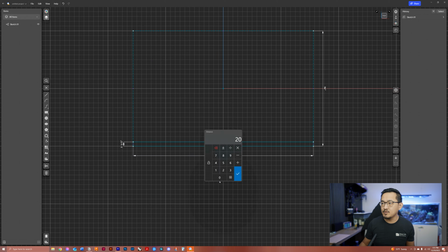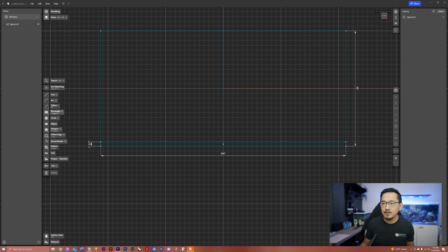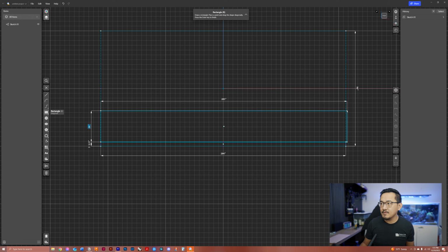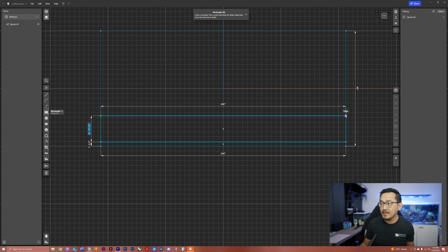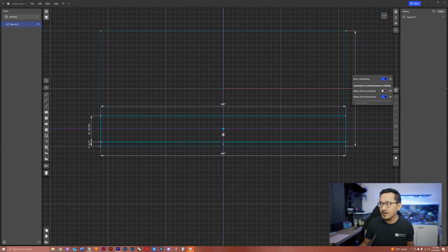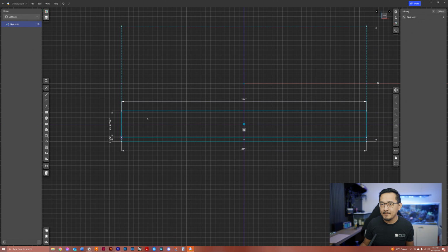It's great that you go back and check your work before moving on, making sure that everything is tied together and moving correctly. So let's go back to 204. And then I'm going to draw the upper cabinets. I'm making sure for these rectangles that I'm hitting that edge point there, as you can see. I want to make sure that the point is locked onto the edge. That way it gives me this automatic coincident constraint. Instead of going in and doing it manually, it's already set to auto constraint, which is nice. I don't have to worry about it.